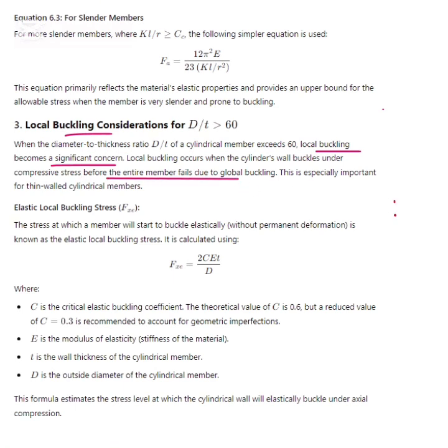For example, this is the member. Instead of this member buckling as a global member, the tubular walls can locally buckle because the diameter is too large and the wall thickness is too thin. Then it has more susceptibility to this kind of local buckling.